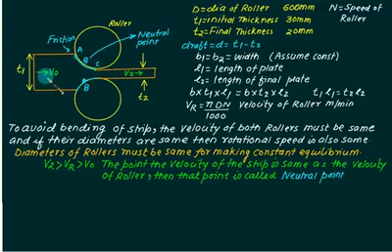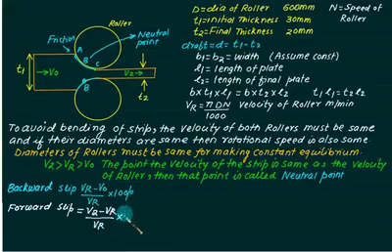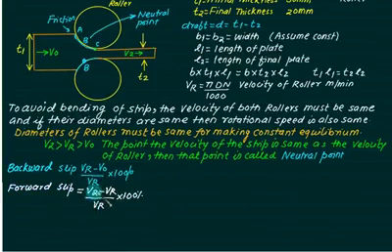So there is a slip from point A to point B, similar to backward slip, and we have forward slip. At point C, velocity equals V2, and at point B, velocity equals VR. So V2 is more than VR, so we have forward slip. It is defined as the velocity at point 2 minus the velocity of the roller, divided by the velocity of the roller, multiplied by 100%. Just remember, every time it is divided by VR, the neutral point. So all velocities you have to compare with the neutral point. This one is also a positive value, as well as this one.